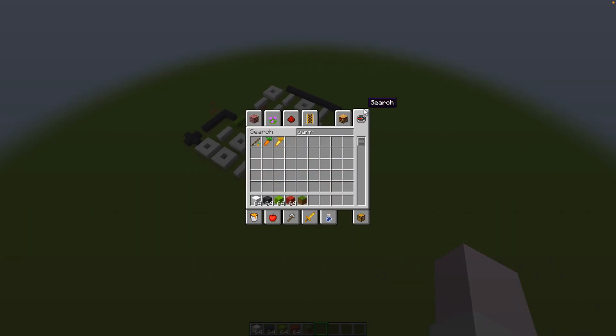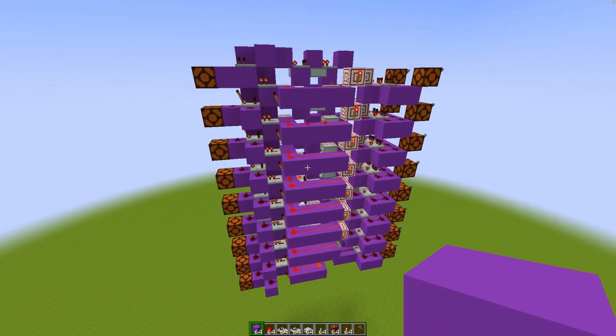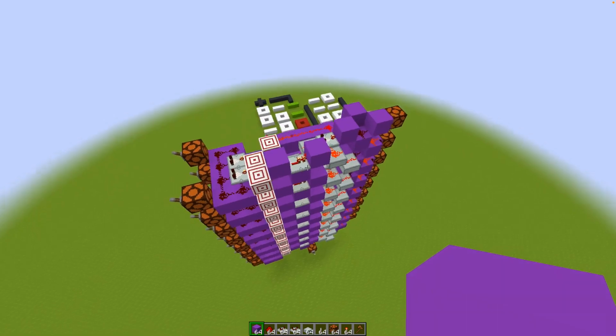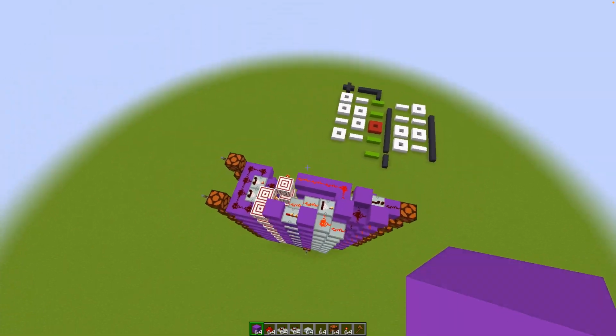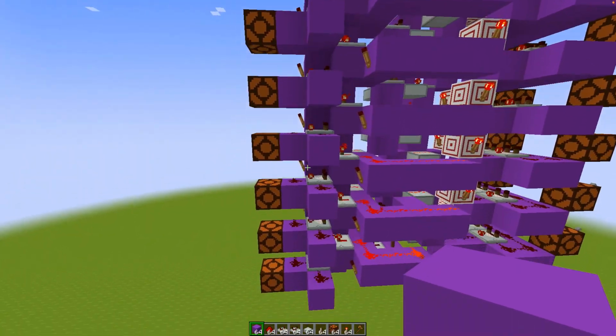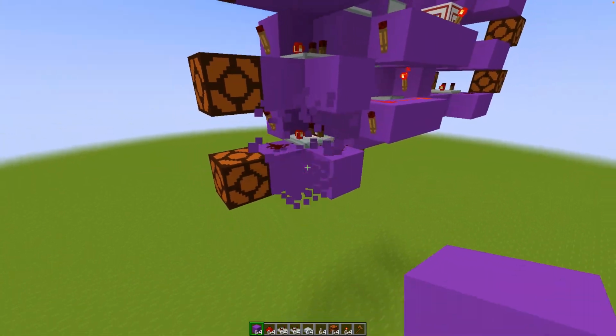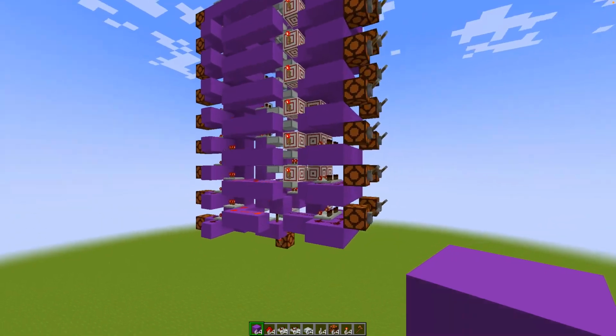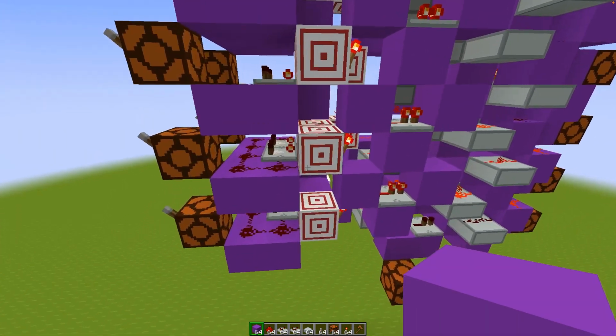And before we can do that, I need to show off how a carry cancel adder does things differently from carry look ahead. Okay everyone, here is the carry cancel adder that we will be building. It's incredibly small in my opinion. And by the way, this final XOR right here is actually made by Benny's Cube. You should check out his channel, there will be a link in the description. The rest of it is not really that original.